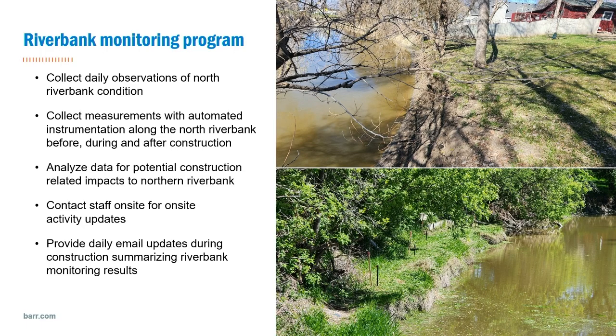If we had some kind of exceedance or some kind of movement, somebody on site would go out and check the riverbank. They would look to see if there were any scarps developing and take measurements if something had moved. And then we provided a daily update during construction. We also had homeowners that were constantly doing their own monitoring of the riverbank on their property.